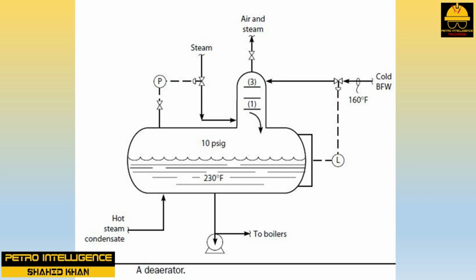In response, the steam pressure control valve also opened. But when the cold BFW level control valve was 40% open, the steam pressure control valve was 100%. Steam flow was now at its maximum. The pressure inside the deaerator started to drop, as there was not enough steam flow to keep the water in the drum at its boiling point.